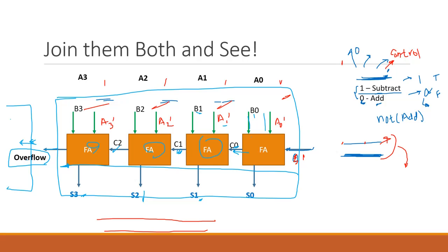So imagine if you are using 16 of these blocks for a 64-bit addition. Just imagine how long it will take. So let's see if we can generate this overflow bit faster so that the next block doesn't have to wait for so many operations to happen before it can start running.